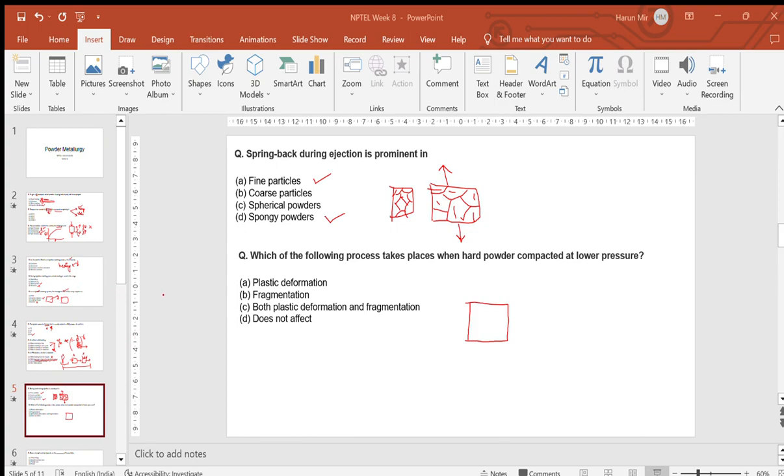So now we have to compare the two mass flow rates. First we'll write the mass flow rate for a cylinder. P is the same for both, eta is the same for both. Now k will be 128 L divided by pi d raised to power 4.